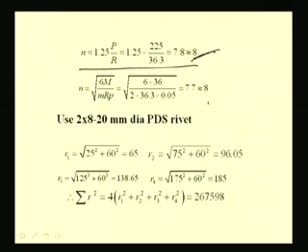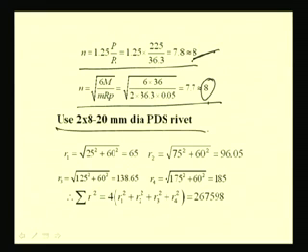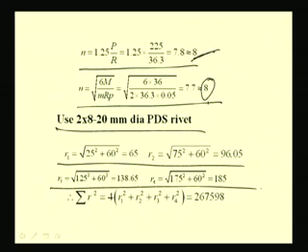That means 8 rivets are required from load point of view, and from moment point of view it requires 8 rivets with 2 rows. So, finally, we are providing 2 rows and 16 rivets in total, and according to that the R1, R2, R3 and R4 values can be found out, and summation R square can be made.